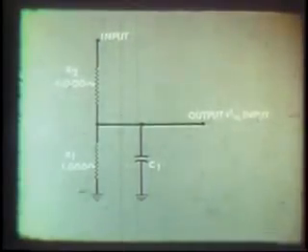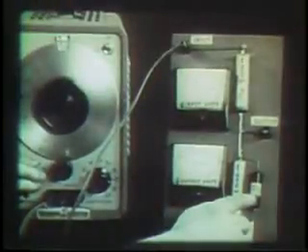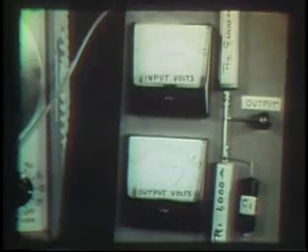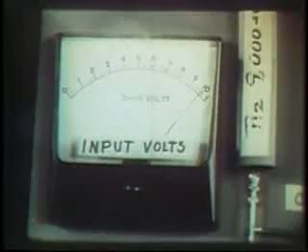At DC and low-frequency AC signals, this capacitance has little effect. As the frequency of the signal is increased, however, the reactance of a capacitor decreases, and we find that C1 is bypassing part of the signal around R1. As a result, we find that this voltage divider is no longer linear in its response to various frequencies.